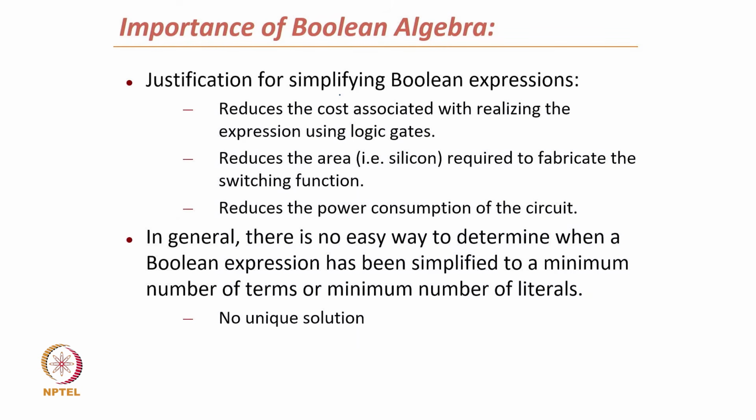Simplifying the Boolean expression reduces the cost associated with realizing the expression using logic gates. It reduces the area as we just discussed and reduces the power consumption. Though in general there is no way to determine whether a Boolean expression has been simplified to a minimum number of terms or minimum number of literals. So, there is no unique solution if you optimize these Boolean expressions.